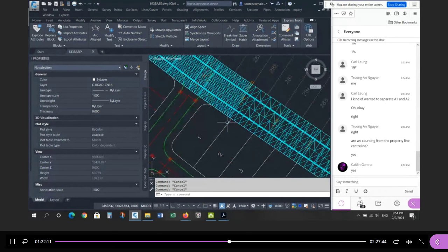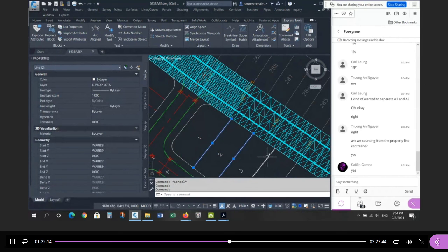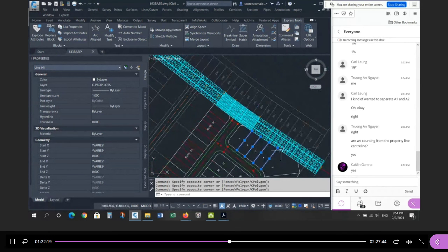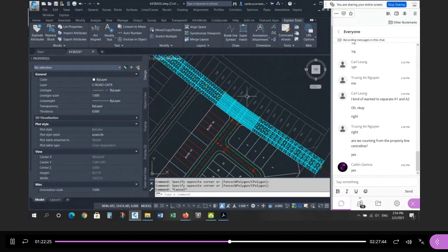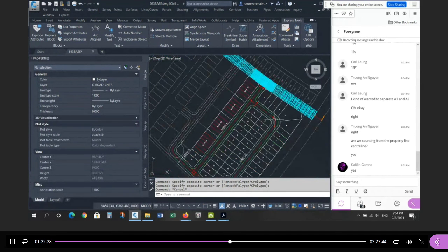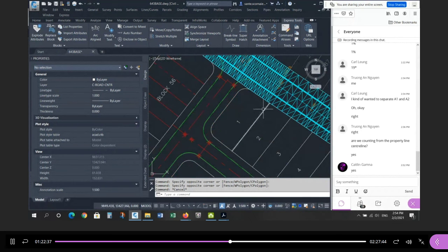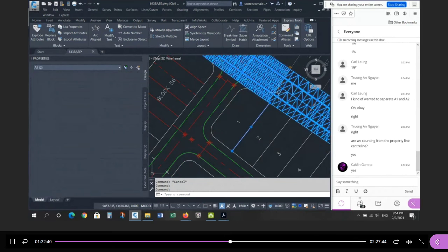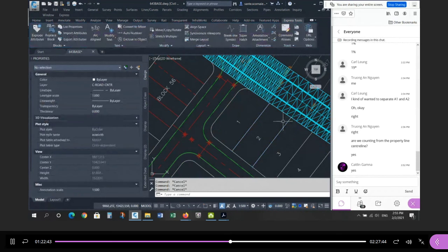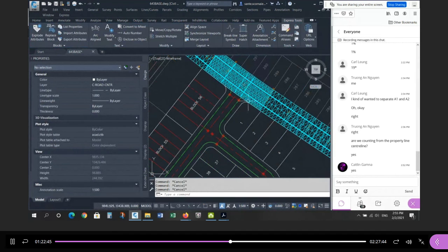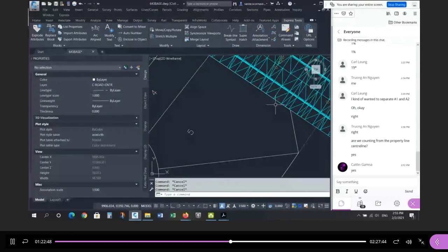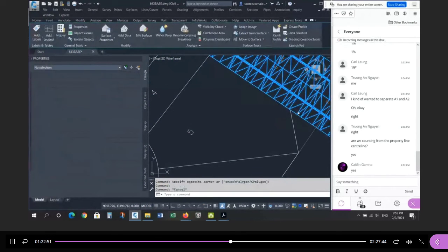The other thing we can use this surface for is to get the elevation at the back of these lots. See these blue dots? 1, 2, 3, 4. We can get those elevations from this surface now, same way we did when we did our grading exercise. As a matter of fact, all the front lot corners inside, and all these rear lot corners, because they're on a right-of-way, are going to come from the corridor surface model. Right? So this elevation comes from this surface, and this elevation comes from this surface. Okay, so it's not only for the design of the profile, but for the design of the grading, right? The elevation right here comes from this road, okay?